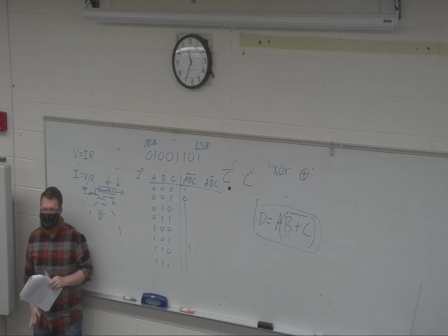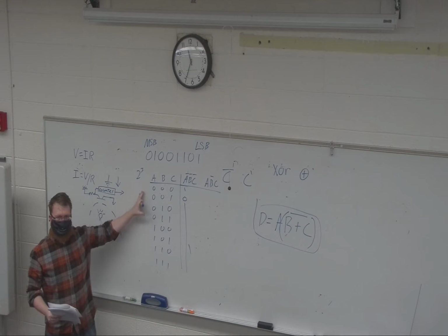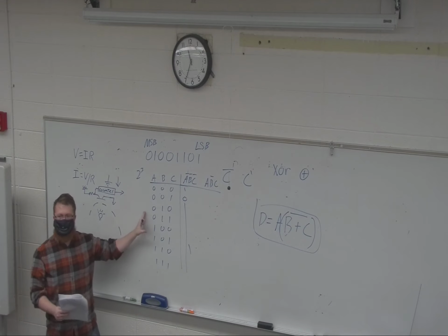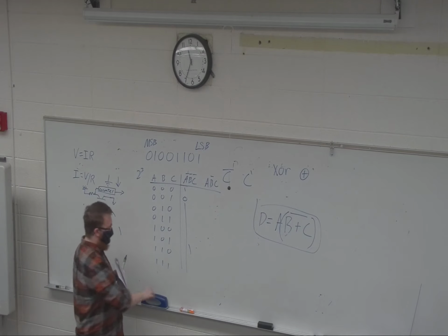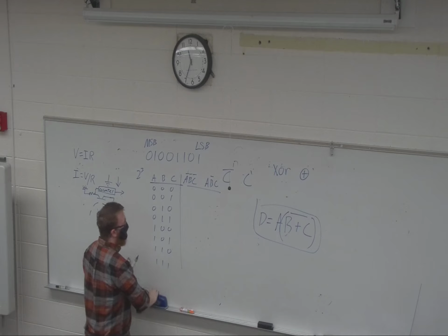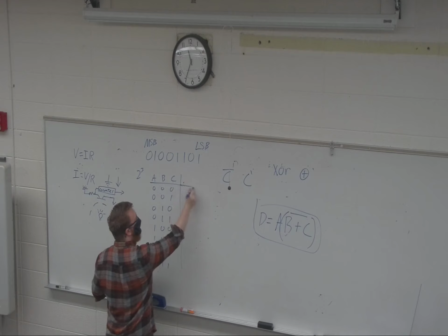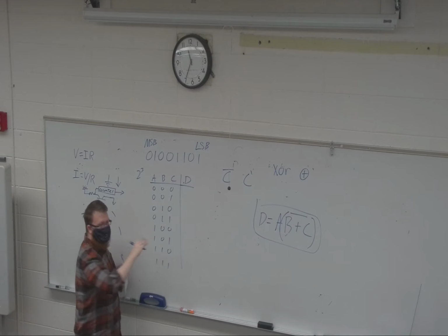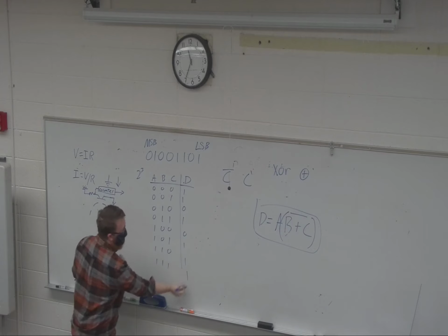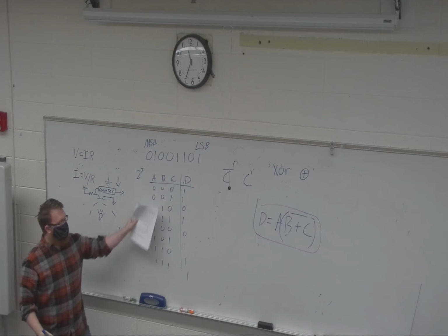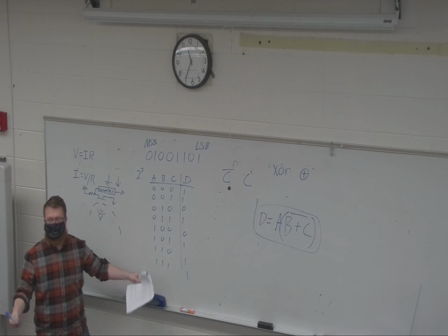I think I'm going to call it there, and we'll pick up with some of these min-terms, and we can start using truth tables next time to start writing logical equations. So I can start describing a function. So if I have a truth table, and I'll give you just a little sample, we'll ignore these. So this is how you do the opposite direction. This would be a really messy one because look at all those ones, right? The fewer ones there are, the simpler the expression is generally.